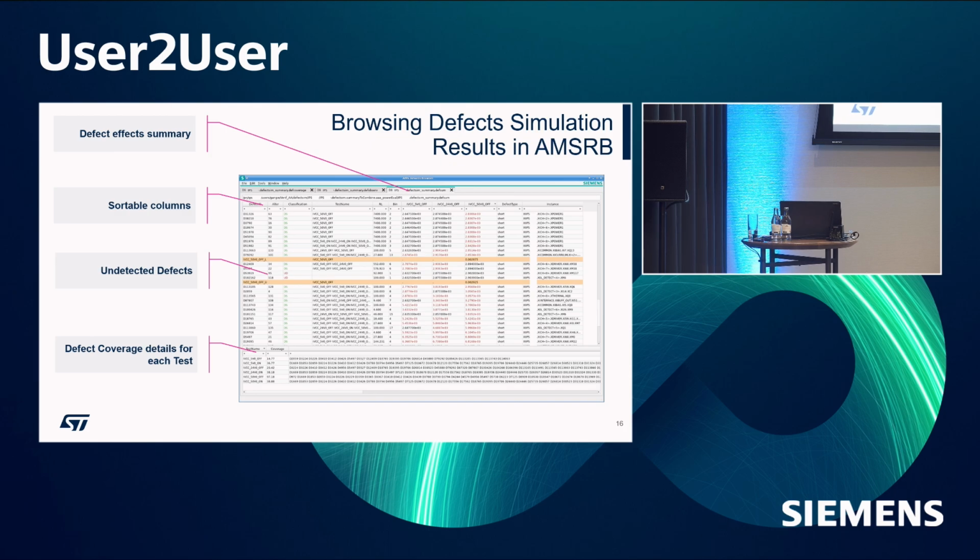One of the first things to be noted is that when you come to the test name spotting the defect, you can notice that maybe, if you're lucky, there is one single or a very small number of tests that will cover the majority of defects. In this case, you are able to reduce the test number, to reduce the redundancy. So you optimize your test suite, you optimize your test time.